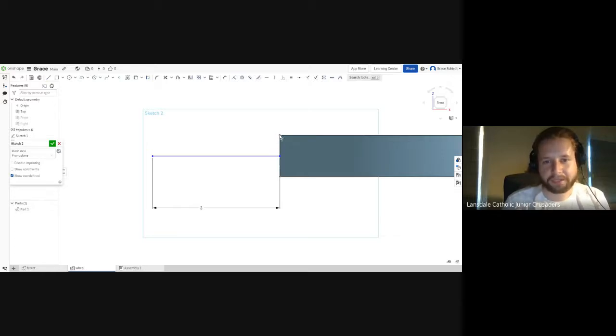Click the top point. Yep. You're on the right track. Click the top surface of the, yep. And make those two coincident. There you go. Make sure that top line is construction geometry. I think it's not right now. There you go. And now to make that thing centered, which constraint do you think you're going to use? Equal? Yes, very good. So you're going to make the top line equal to the bottom line. And now it will be centered no matter what the height of the wheel is, right?